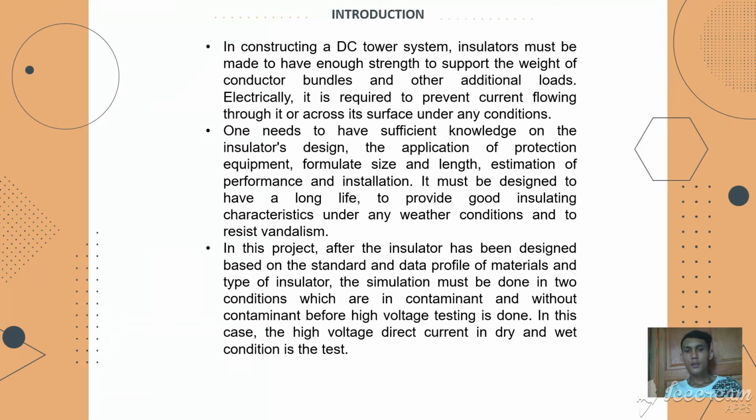Okay, the last one is, in this project, after the insulator has been designed based on a standard electrical profile of material and type of insulator, the simulation must be done in contaminated and non-contaminated conditions before high voltage testing is done. This can be done under dry and wet conditions.